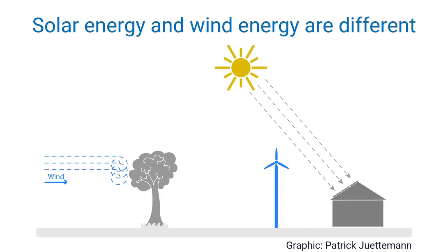Solar radiation comes from the sky above. Only objects very close to the building will cause shading. But wind energy, usable for the rotor of a windmill, moves parallel to the surface. So also objects that are 100 meters away or even more distant are reducing the energy supplied by the wind. So on this side here, solar energy can be used, but not a small wind turbine.